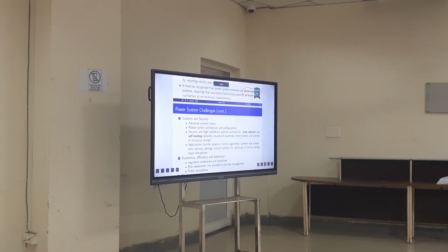So you as an electrical engineer should be in a position to explain this to the person. Many people don't know electrical engineering. Okay. So they will say, I will charge my vehicle from the solar PV. Why is it not charging? It's not possible. How can a 3 kilowatt system charge a 7 kilowatt charger? Is it possible? 3 kilowatt is the maximum power. Most of the time the solar will generate around 1.5 kilowatt of that because of the capacity utilization.